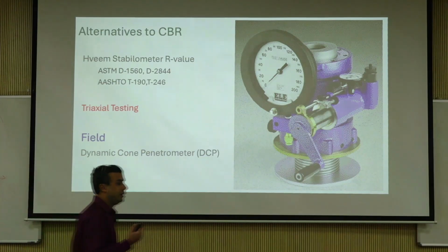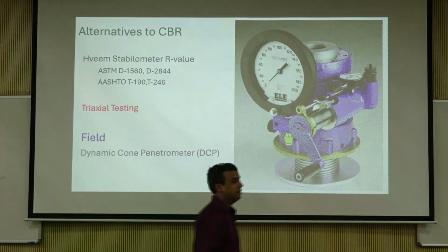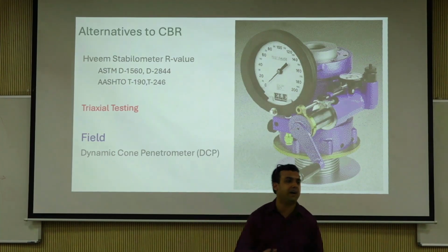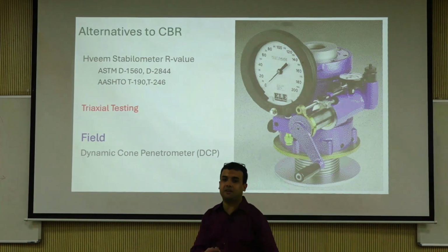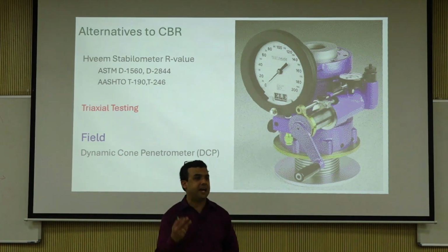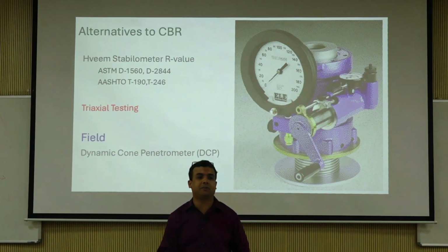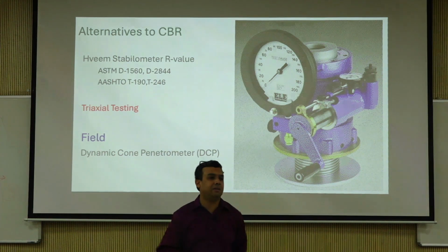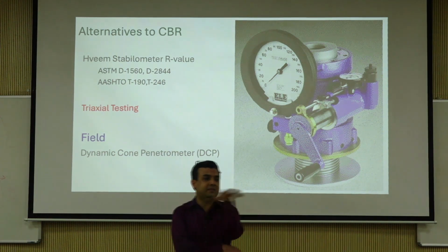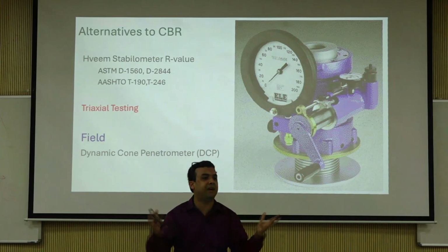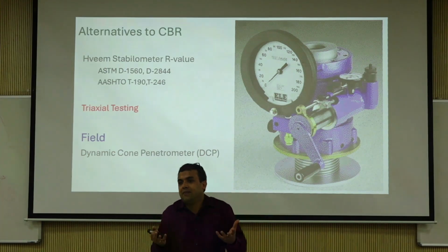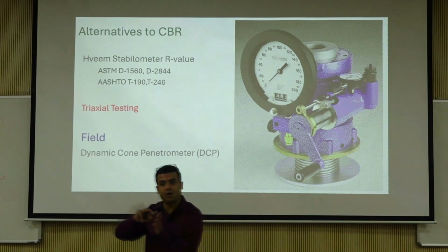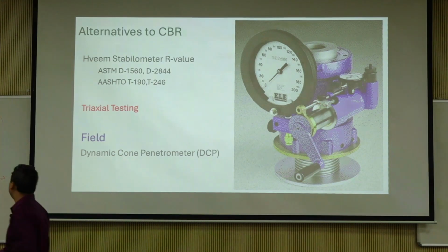Let's say there is an agency dealing with the district of Khordha, and they encounter 4 or 5 different types of soils, and over the years they have tested the soils, characterized them, and developed a database saying that, okay, my relationship is that resilient modulus at some kind of stress state is about 2500 times CBR or something. That's okay, because they have done it for their soil. They know what is representative. We cannot use it widely. It's just not something you should be doing.